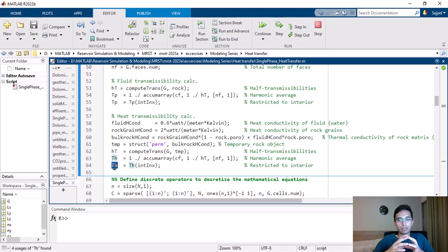And as you know, we have two, actually, let me talk about it later. But for the transfer of heat in porous media, we usually consider two terms. One is the advection term, which I sometimes call the forced convection term, and there is another mechanism that contributes to the transfer of heat, and that is the conduction term. I'll show you these terms later in this video.